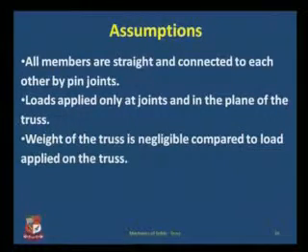If your loads are in the plane or perpendicular to the plane of the truss, then it becomes a problem of a space truss, which we are not going to cover. So all the loads are in the plane of the truss, and only then do I call it a planar truss. The third assumption is that the weight of the truss is negligible compared to the load applied on the truss. That is, if I consider the total weight of the truss, which is constructed out of steel, then it is negligible, and therefore we can neglect that load when we are considering the forces of the members to be found out.